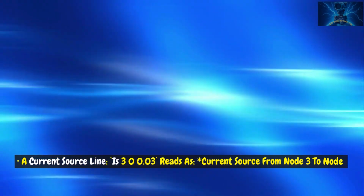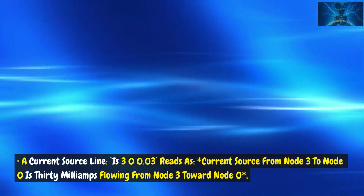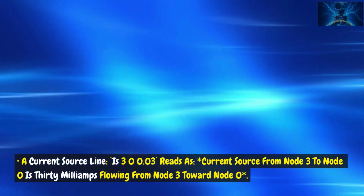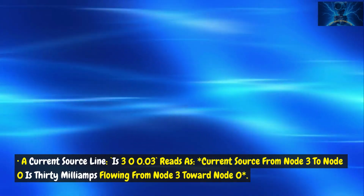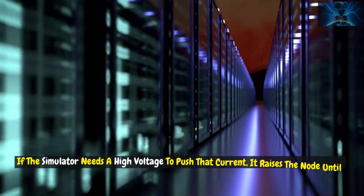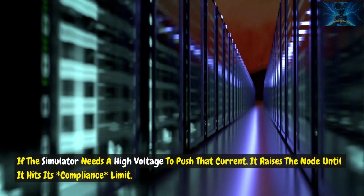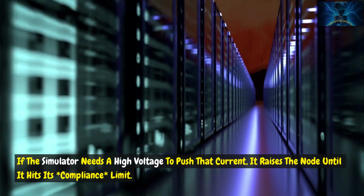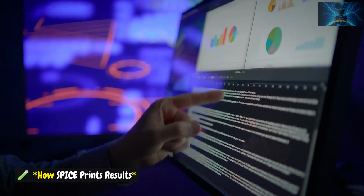A current source line, I1 3 0 30m, reads as: current source from node 3 to node 0 is 30 milliamps flowing from node 3 toward node 0. If the simulator needs a high voltage to push that current, it raises the node until it hits its compliance limit.